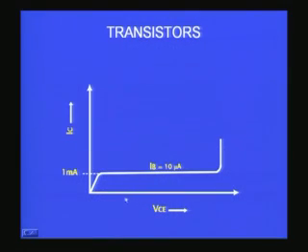Now, you can see I am plotting on the x axis VCE, the voltage between the collector and the emitter, and on the y axis IC, the current at the collector, for different IB values. This is one value of IB I have maintained, and you find as we increase the VCE, initially for a very small voltage variation the current increases linearly, and after that, for example in this case when the current IC reaches 1 milliampere, you find irrespective of the voltage you apply on the VCE, the current remains constant.